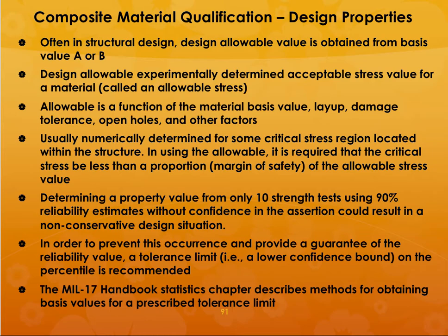And we need to do that in a conservative fashion. So if you do it with a smaller number of samples, you are going to have a non-conservative design situation. So in order to prevent that, you have to have a tolerance limit on the percentile, which is recommended, and the MIL 17 handbook will describe that, and I will post that in your bibliography.